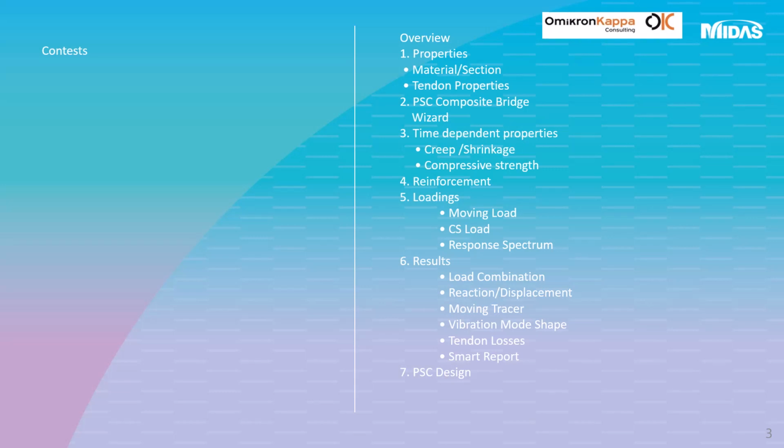We are going to start modeling the bridge by defining the properties for material and for sections. Then we are going to input the tendon properties. For the deck and the piers, we are going to create them by the use of the PSC Composite Bridge Wizard.